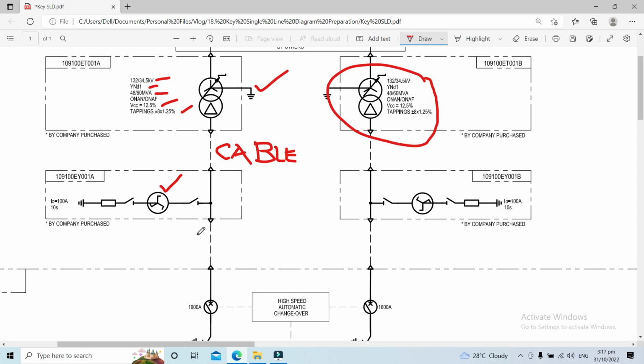So we also have, on both sides of the incoming feeders, the zigzag transformer, and it's connected so that we will have a grounded secondary side of our line. We connected here a neutral earthing resistor. It is rated 100 amperes. We call this one a high impedance neutral earthing resistor.